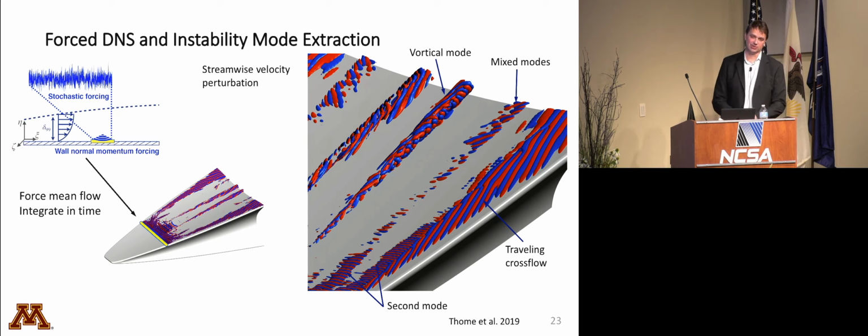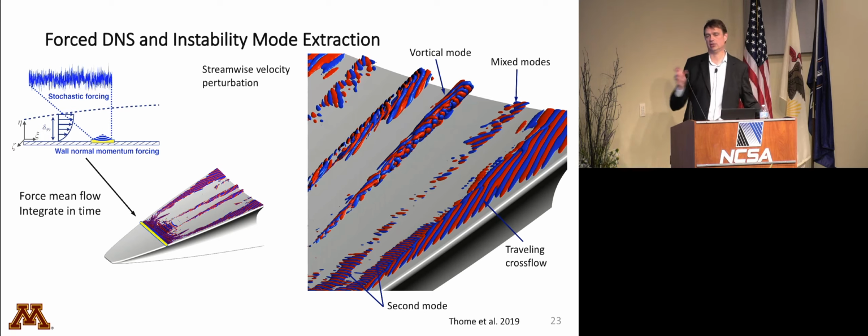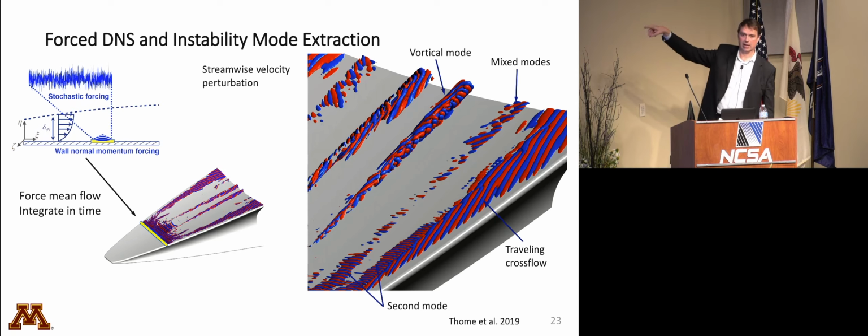I'm working with Professor Joe Nichols at Minnesota, and basically we can now take the derivative of that flow field with respect to the state, and apply all sorts of interesting linear stability or linear systems analysis methods to that Jacobian. One of those is an input-output approach where we have this huge Jacobian that represents how the flow field responds, and we can poke it at one place and measure the output, and project the output back onto the input. This is going to allow us to connect that particular disturbance to a particular forcing quantity. And that's what's going to be really exciting.